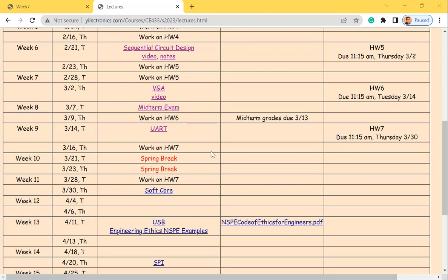USB to where? So the Basys3 has a USB, and the UART data will be sent through the USB out to somewhere else. If you plug into the computer, yes, it's going to perform like the Arduino board, which has a UART and USB converter in the middle, because you have been doing that to upload your code to the FPGA all the time. So definitely we can use that port to communicate with what? What's the other terminal of the USB port? That's a computer, right? So that's one way to do it.